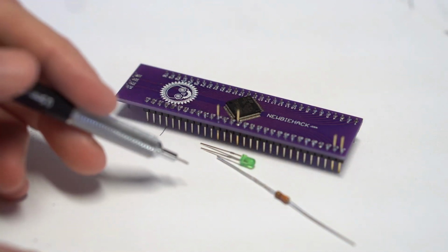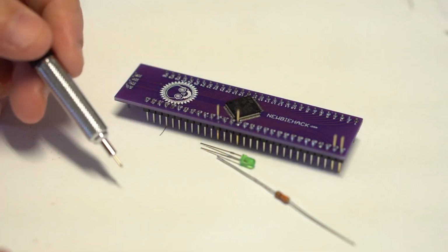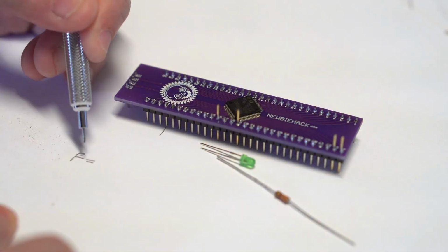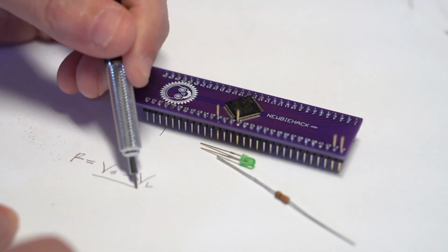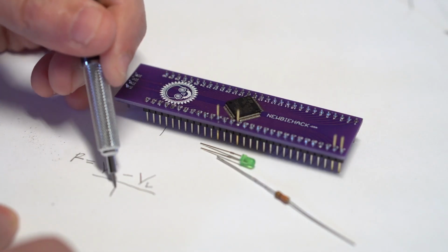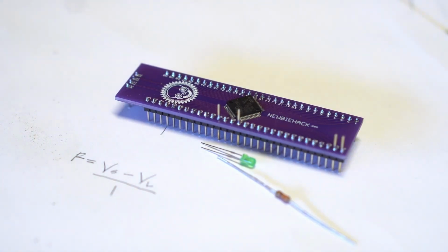If you want to figure out the actual resistor you need to use, you can figure that out using this formula. The resistance is equal to the supply voltage minus the LED voltage, which you'll need to know, divided by the current. If you use 0.01 amps for your current, which is a conservative number, the supply voltage is 3.3, and I use 2 volts for the LED voltage. You'll have to look at the data sheet for your LED if you are using a different LED. And my resistance value came out to be 130 ohms.